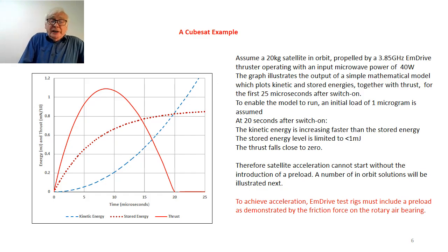Therefore, what we're suggesting is that if you have a satellite in orbit, absolutely no loads on it at all, you simply cannot start up the acceleration of the satellite without the introduction of a preload. How you actually do this, we will cover in the next slide. There's a number of solutions to this, but it's also important to recognize that if you're actually going to measure thrust on a test rig, you also need to apply a preload.